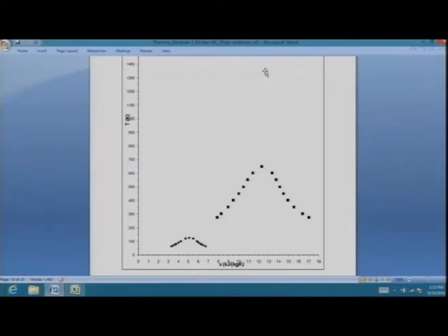So 1400, 1700, 1900 Kelvin, which are temperatures we are talking of in combustors and burners, we are far away from this dome, and we can say that I'm far away from the critical point. Anything like this, I can quite happily accept as ideal gas behavior. In fact, that's what we do for nitrogen. The critical point of nitrogen is 126 Kelvin. We live at 300 Kelvin plus, so we are more than 2.5 times the critical temperature of nitrogen.